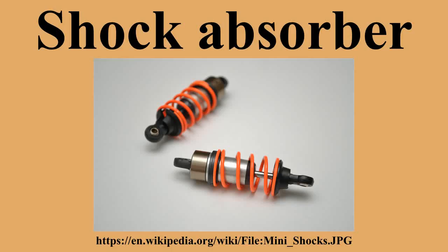The result of this alteration is a dramatic reduction in foaming or aeration, the undesirable outcome of a twin-tube overheating and failing, which presents as foaming hydraulic fluid dripping out of the assembly. Twin-tube gas-charged shock absorbers represent the vast majority of original modern vehicle suspension installations.